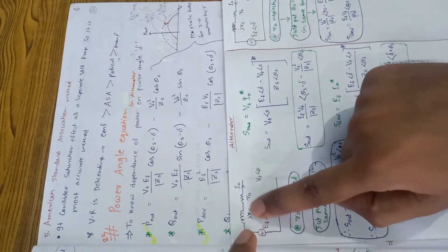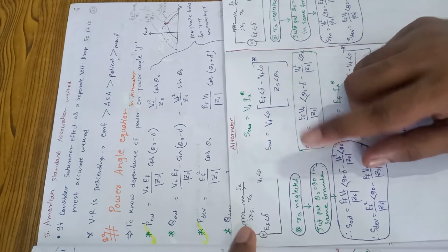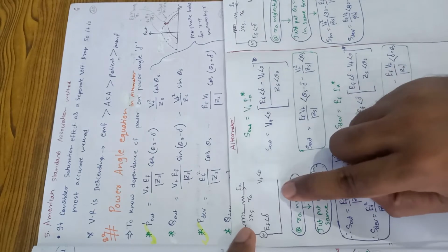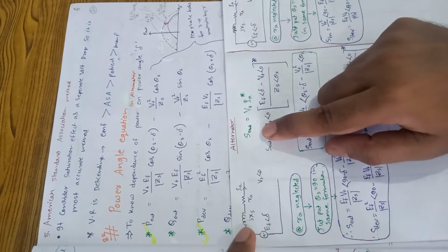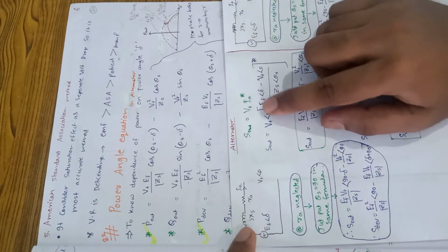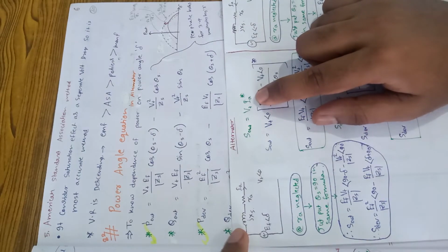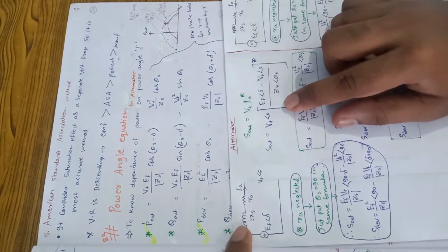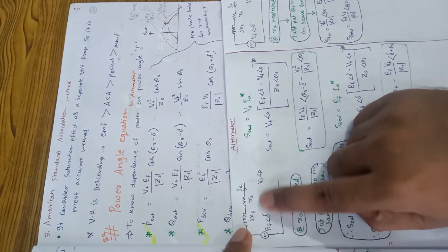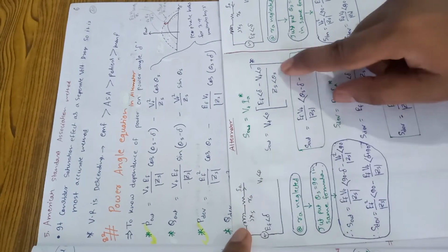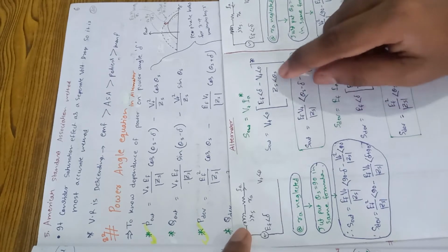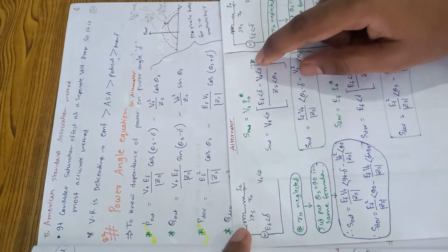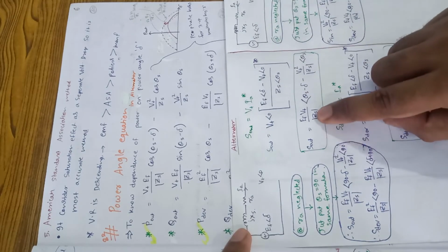This is the equivalent circuit of the alternator. When we talk about output power, the current is coming out. Output power means S out will be V I conjugate. We already said that current should not appear in the equation, so we'll remove this I. We can remove I by taking this minus this upon the impedance. After simplifying all the conjugates, we finally get this expression.